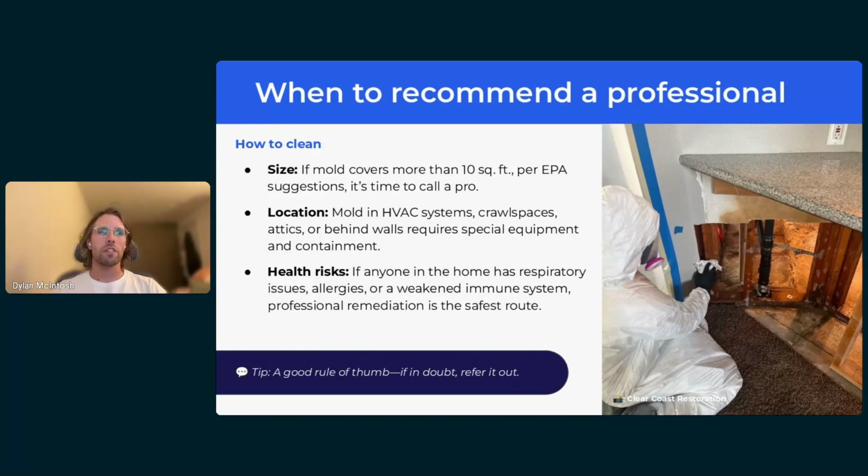I've seen cross-contamination issues where prior to the remediation, there was no effect, no detectable levels of elevated mold in adjacent areas, but the containment wasn't successful, or the methods used for moving materials in and out of containment weren't maintained very well, and they actually created a cross-contamination issue during and after remediation. So that's why it's important to test adjacent areas as well, to make sure that cross-contamination hasn't occurred.